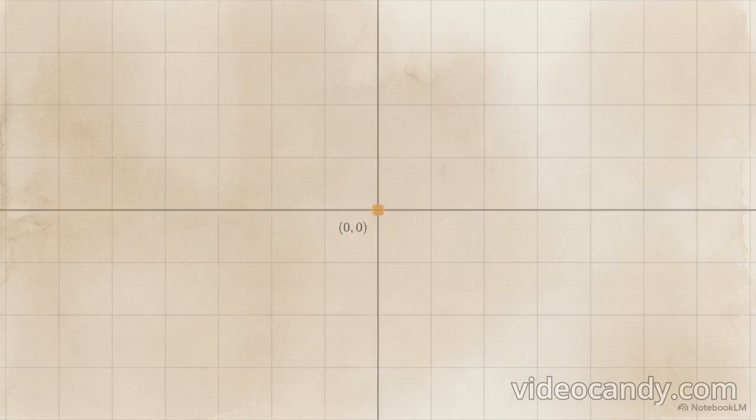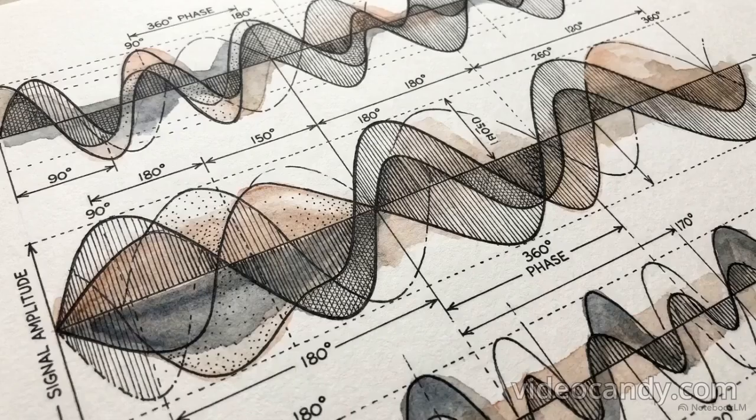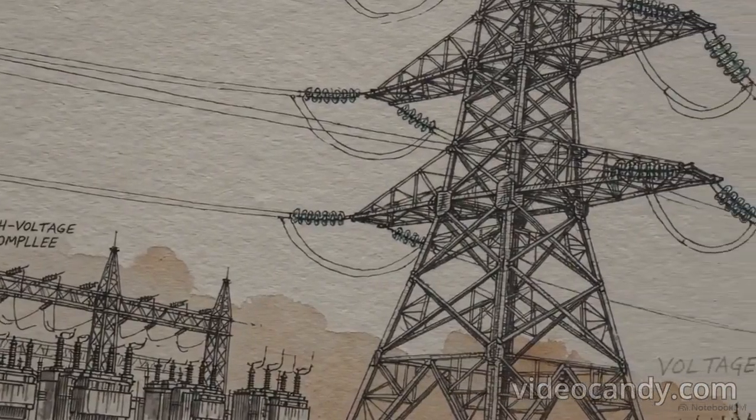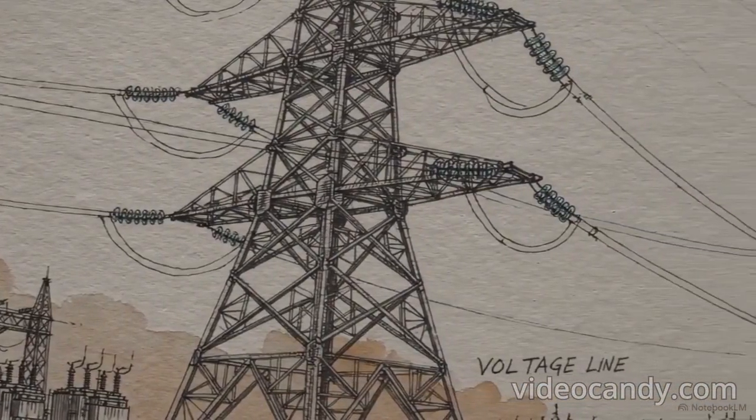To synchronize the primary and secondary behaviors, we need a single magnetic baseline. We establish the mutual core flux as our horizontal reference, serving as the anchor for every other vector in the system. By tracking the exact phase angles and lengths of these phasors, engineers can predict exactly how internal impedance will warp the output voltage before it ever leaves the substation. The core flux remains the constant reference point.